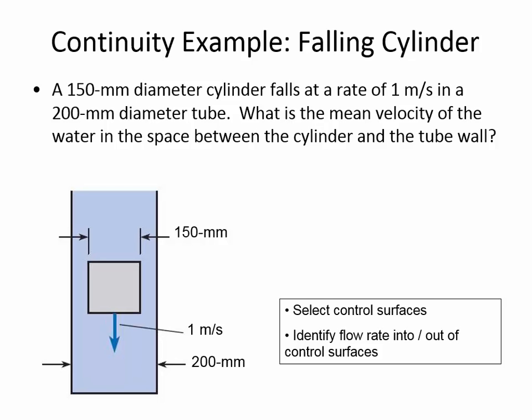What we could say is that when this cylinder goes down, it's pushing the water someplace. I see Stuart nodding his head. Where is it pushing the water? As it goes down, that solid cylinder is displacing some water. So where does it go? It's got to go around the sides. Exactly. So in this problem, the way to solve it is look at defining a control volume. So you draw a control volume, and then you say, how is fluid going into the control volume?